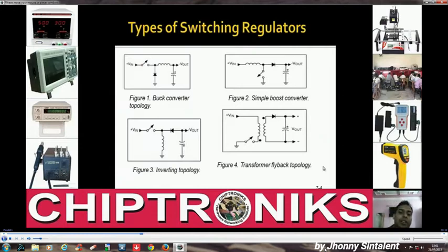In this slide is an example of a buck converter. This is an asynchronous buck converter, which doesn't employ any MOSFET. This is Vin, this is a diode, and this is one inductor. We'll discuss the working of this section also. When the switch turns on, the current would increase slowly, whereas if it gets turned off, the current would reduce, but it will reduce slowly.